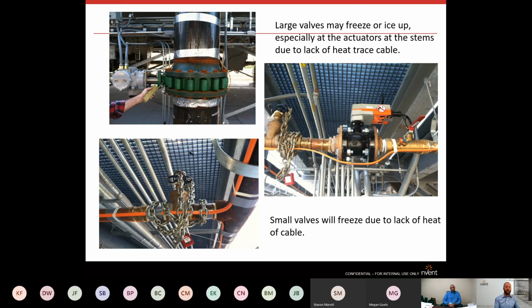so that you're not putting too little insulation on and then trying to compensate with more heat, or going overboard on the insulation when really you could just put a few more watts per foot and go a whole lot less. We call it heat tracing system optimization: finding that marriage, that right amount of output and that right amount of insulation that makes sense monetarily and heat loss wise.